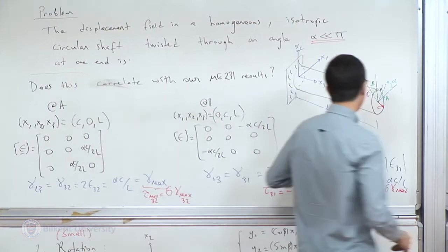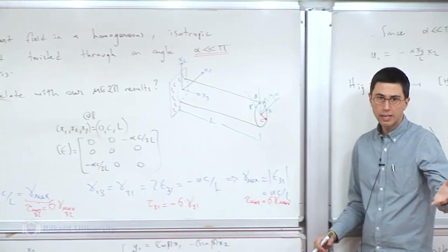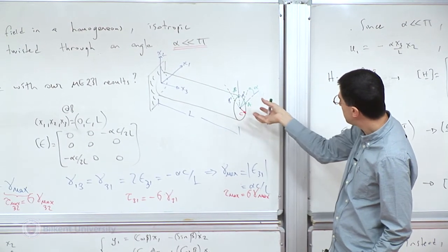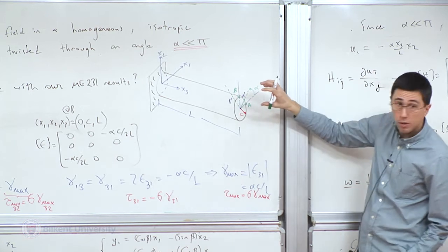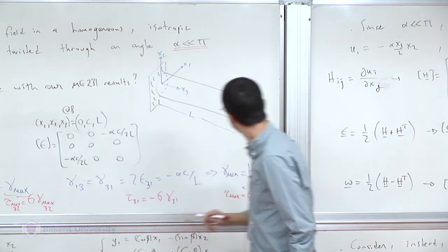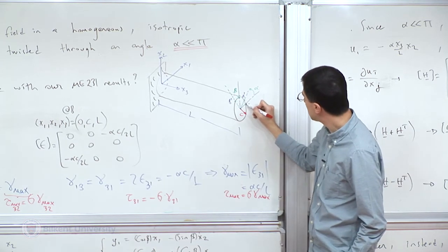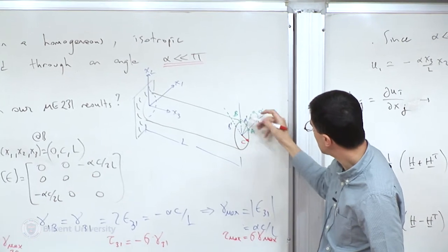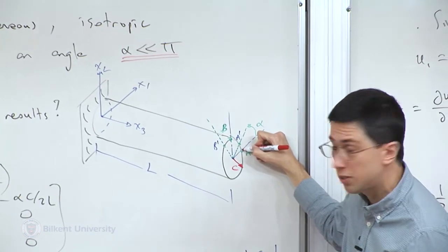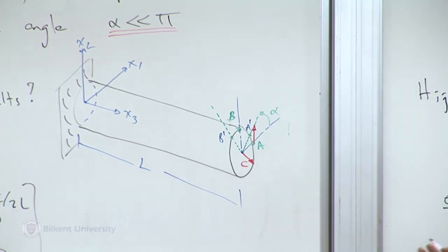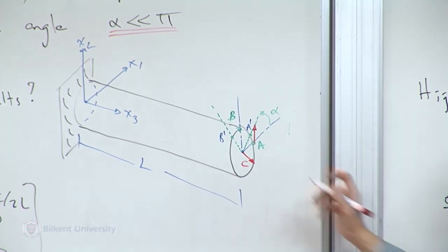Well, the sign indicates the following. So I am twisting. Right? So if you like, have a look here for a second, just to refresh your 2.31 knowledge. I'm twisting counterclockwise. So at this point, let's pick the red color. At this point, twist is up, or counterclockwise, the shear stress is always tangential to the surface. So it should be upwards, right? That's the direction of twist.